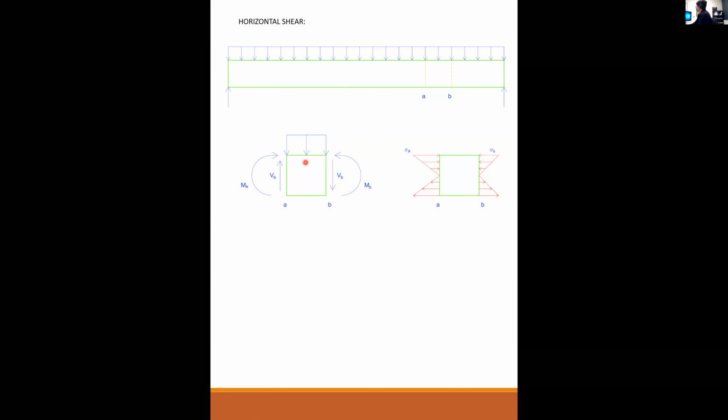What is important here is that A is closer to the midspan. So A is going to have a larger moment than B, right? And we just drew a bunch of shear and moment diagrams. We saw what the moment diagram looks like for this sort of beam. You know that the maximum moment is at the midspan. So any point closer to the midspan is going to be a bigger moment. Any point closer to the reaction is going to be a smaller moment. So the moment at A is going to be larger than the moment at B.